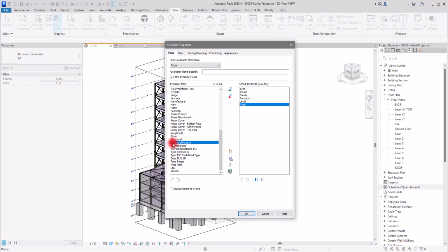You always have this, and you can add the material of that section, the main material of that like floor, wall, or any category to your schedule too. After this, we have the volume, and if we need any other thing, we can come back to here. For now, I think this is okay.